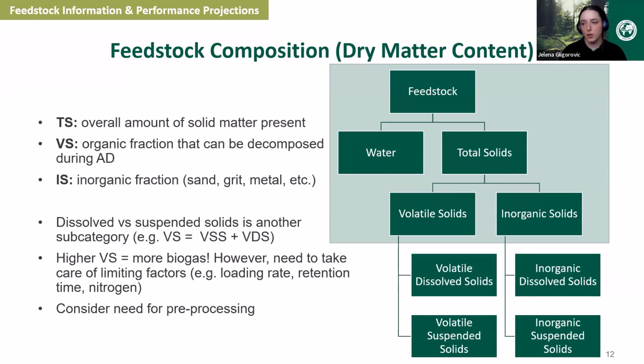So dissolved versus suspended, you can think of it as if you have a glass of muddy water and you let it sit for a while, the mud settles at the bottom, but you still have brown, unclear water above the mud that's settled at the bottom. So that mud that is at the bottom, that's kind of your suspended solids. And then the material that's dissolved within the water above, kind of what you can think of for dissolved solids.